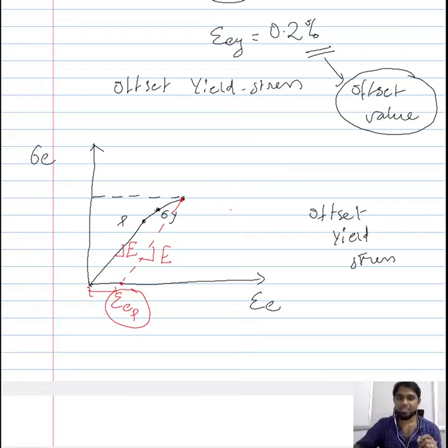And of course, even when you unload it, the behavior of the material would retrace the line that we considered for calculating the permanent strain within the material. So for this load here, even if you begin to unload the material, its behavior would trace the path that we have considered to calculate the amount of plastic strain within the material.